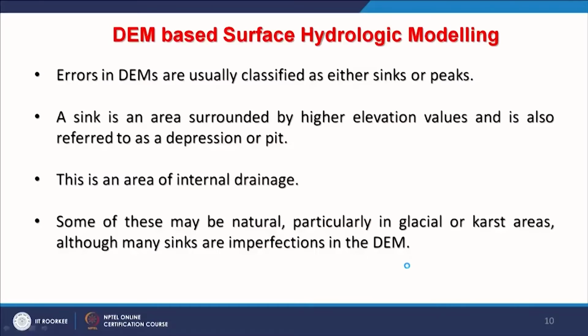So, there the surface hydrologic modeling may not predict as you wish, because it will not follow that assumption. The assumption is that even a single drop of water, if it falls on the surface in a watershed, has to come out through the outlet. So, in many conditions this assumption is not fulfilled, but nonetheless in many conditions it is.